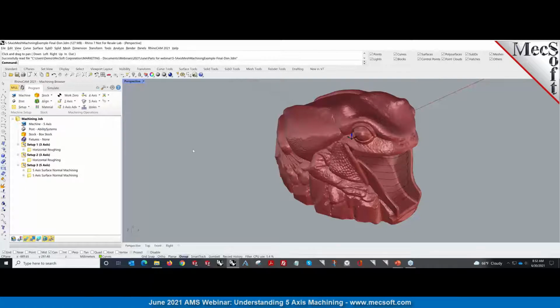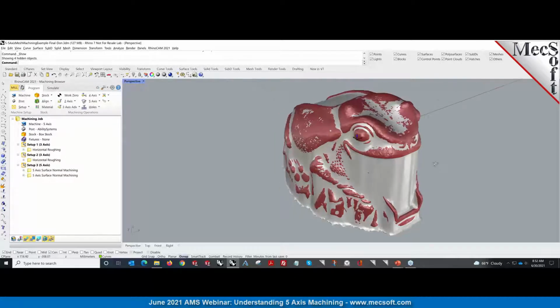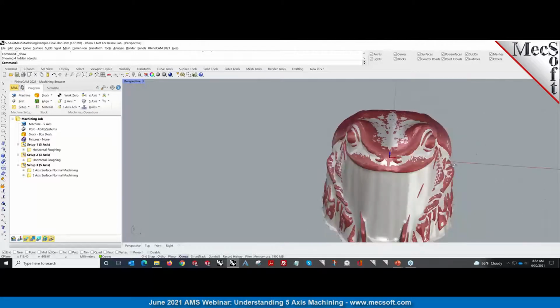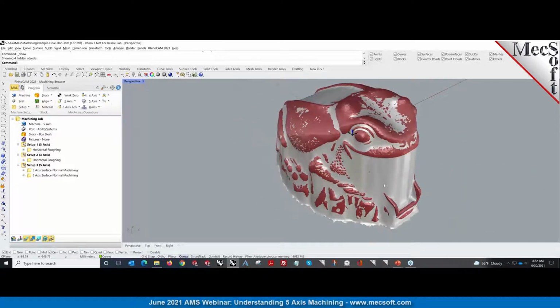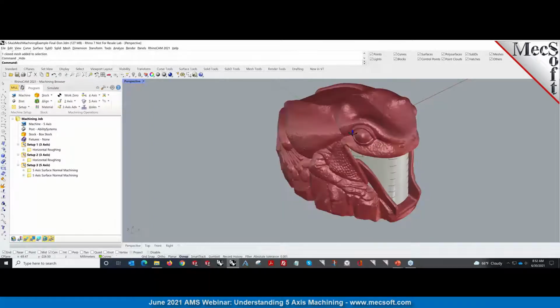What we did was, I'll show you the different surfaces very quickly that we had to create. We used the power of Rhino to create that drape surface. So we did a drape surface. It's basically essentially created a closed surface, and that was the drape. And then I'm going to hide that. And then using our mesh module, we actually offset that surface, created a mesh, and then we offset that mesh, and then came up with these.